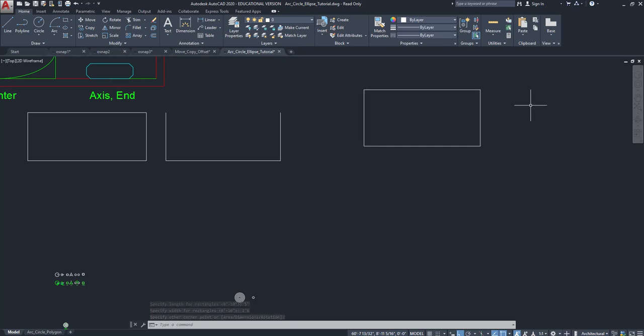So if I re-enter the rectangle command, REC, enter, I click my first point, I come down here to dimension. The length is in the X direction, okay? And then the width is in the Y direction, all right? So if you had accidentally typed 2 foot 6, enter, and then 5 foot, enter, it would have been vertical,